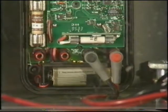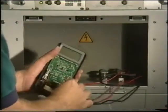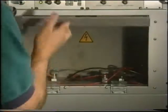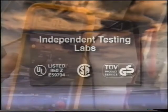The IEC is not responsible for enforcing their standards, so a meter that claims to be designed to a standard may not have even been tested. That's why it's essential that a digital multimeter you use has a label that shows it's been certified by an independent testing laboratory, like UL in the United States, CSA in Canada, TUV in Europe, and so on.